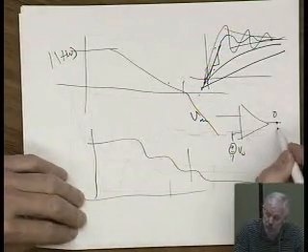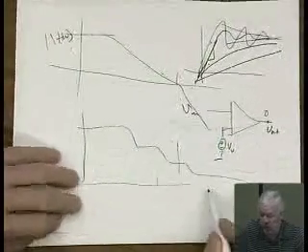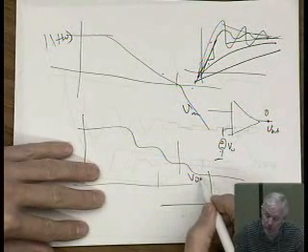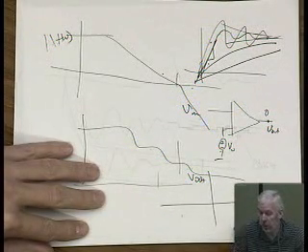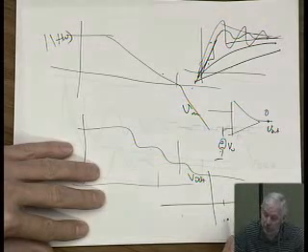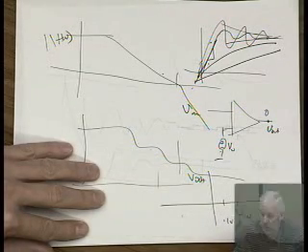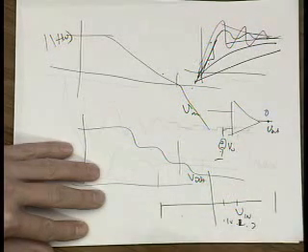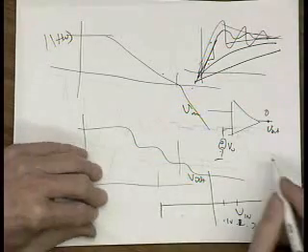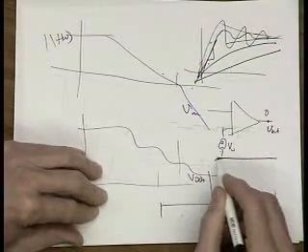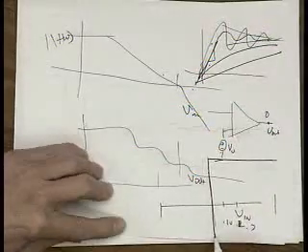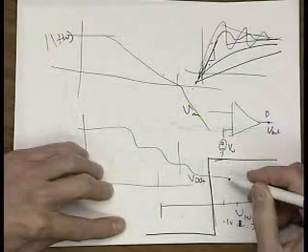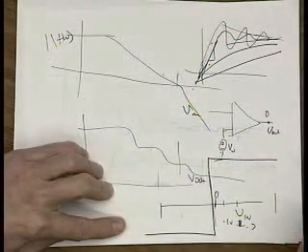Here's your V in, here's your V out. The response is going to be something, if this is V in versus V out on, let's put it on a tenth volt scale, 0.2, 0.3, so this is going from half a volt, minus half a volt, plus half a volt. This response is going to look like this. If you've got a gain of 10,000 or 20,000, it's going to be just a really sharp transition. And it may not be right at 0 volts. This may be 0 right here.